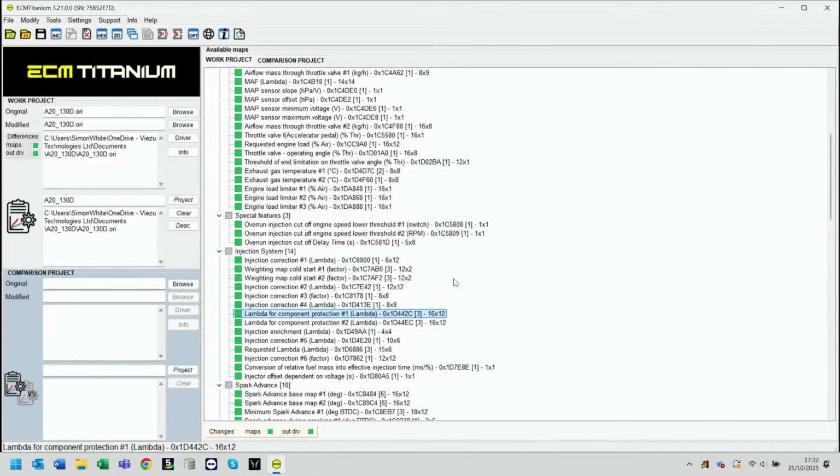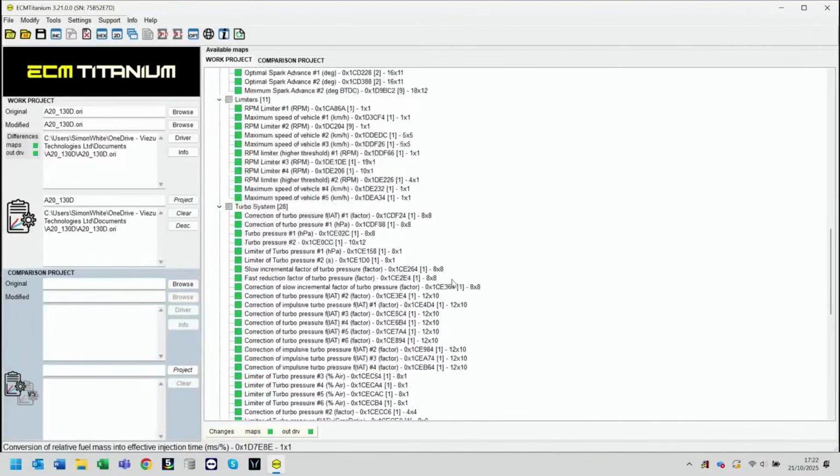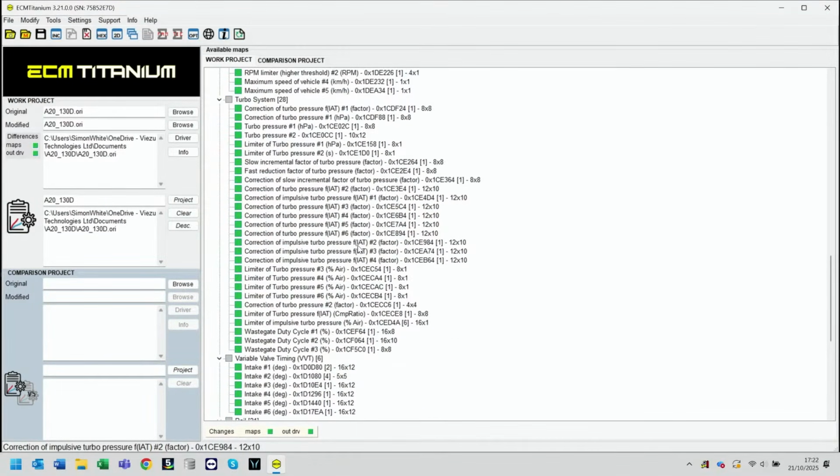Now we can further validate this by going back to our very nice and simple turbo pressure folder, all those lovely maps for the turbo system, because there's a couple of extra maps in here that will basically quantify and validate those higher values. Now before I jump into them, I do want to just cover off a really useful, helpful hint and tip here. A lot of people always ask us, and it's probably one of the questions we'll get in this webinar, and we've had it before in courses, what does the percentage of air mean in real terms?